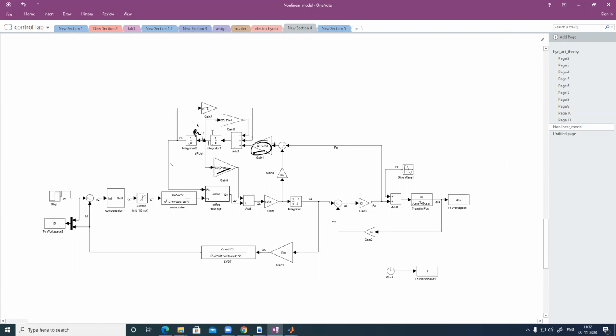So if you are using the linear model in Simulink, you have to use this block there. So this omega 1 square. The transfer function you are taking, you will get like this only. So this is a forward path. So G upon 1 plus GH you have to take. Again G upon 1 plus GH you have to take. Then you will get that transfer function.